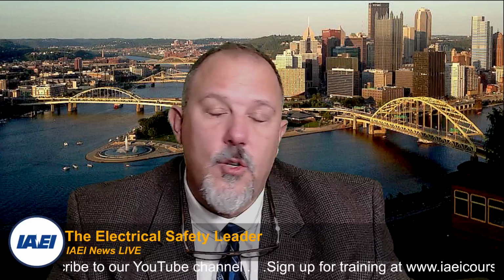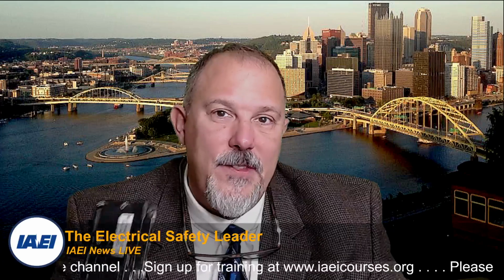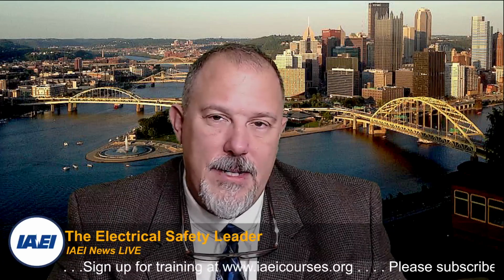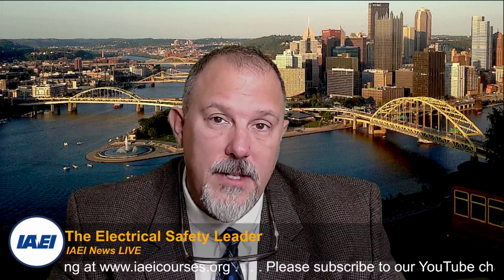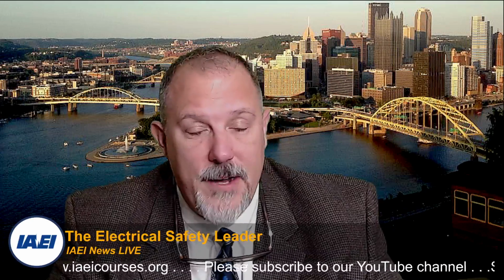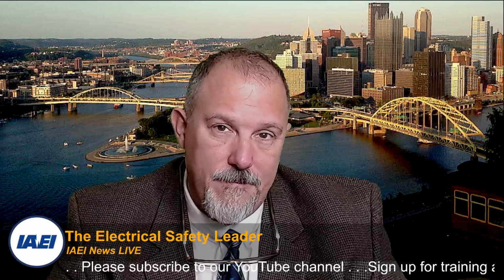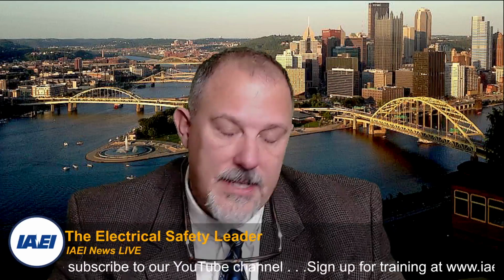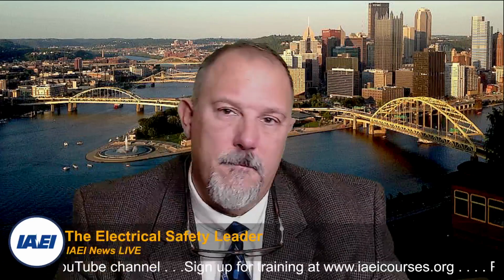I don't need an equipment grounding conductor because all I'm looking at is the hot and the neutral. I don't care about the equipment grounding conductor, whether it's there or not. If you come in contact with it and it passes through your body, that means it's going to find its way back to the source without going through that donut, the sensor. And the same philosophy applies to this receptacle.